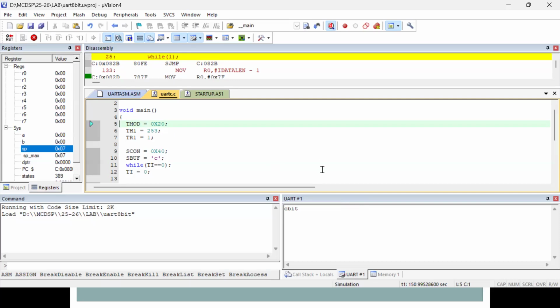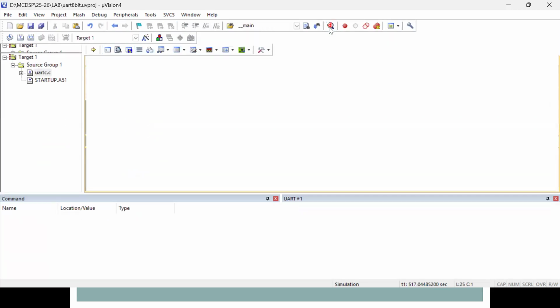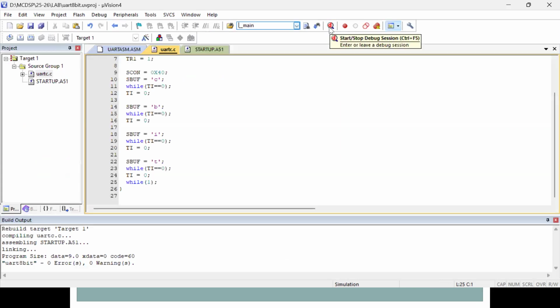Okay, so one more thing here we need to make clear. What about SMOD bit? Okay, so SMOD bit, which is the most significant bit of PCON register. By default, on reset, all the registers are cleared to 0. So SMOD bit is 0 by default. If you want to make the bit different, then program PCON, you have to load the whole register because it is not a bit addressable register. And this is about the transmitter. So next proceed with the reception also. Okay, you need to write a program for the receiver also.